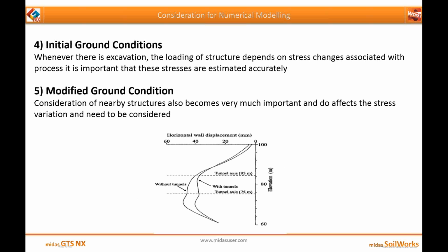Now, the next point of consideration for numerical modeling is the initial ground condition. Whenever there is excavation, the loading of the structure depends on the stress changes associated with the process, and it is very important that these stresses are estimated accurately, and hence the need for numerical modeling arises. Modified ground condition, for example, if you have some building, it changes the stress condition in the model, so you must be able to simulate that behavior too in your model, and then once again the consideration for numerical modeling becomes important.